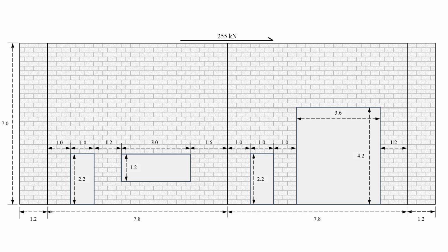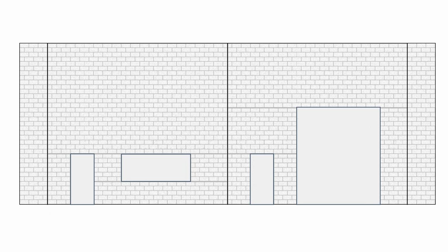You can see here that we're looking at a shear wall that's separated into 4 segments by our movement joints. Now, each wall panel is going to take a portion of our lateral load. This load's directly proportional to the rigidity of each panel. So if there's one panel that contains the bulk of the total rigidity, we also know that it's going to take most of the applied load, such as wind or seismic. So how do we determine the rigidity of each panel?